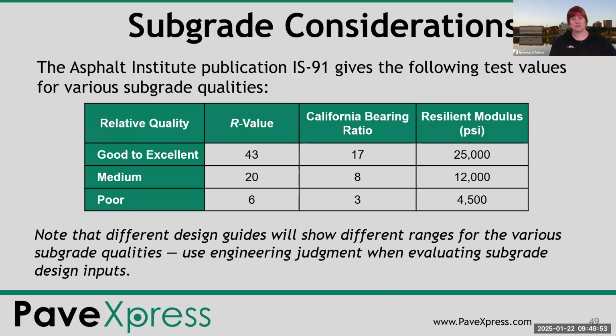And as the resident geotech, I'm going to bust in real quick here and just say that the more important your pavement is, if it is a unique pavement or a brand new pavement, or you are expecting really extreme loads, anything like that, where you really need this pavement to be bulletproof, I would really encourage you guys to do that resilient modulus testing. Have that as part of your exploration plan when you talk with your consultant or whoever is going to be doing that exploration for you, and getting those soil samples.